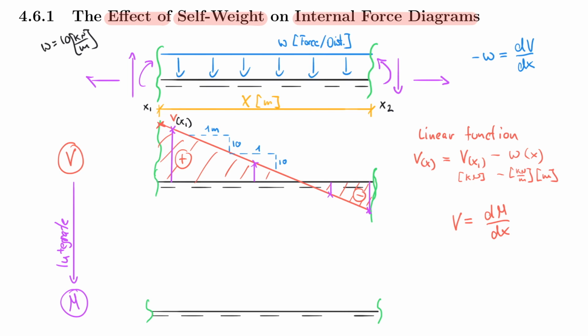And of course, the one thing I never need to explain to my students is that here I have a zero value. So here V of x is really equal to 0, or the shear force at that location is equal to 0. And therefore, everybody understands that when you go to the primitive, or the parent function as I call it sometimes, I have a local maximum or minimum here. And that is something we can often agree on in the classroom.